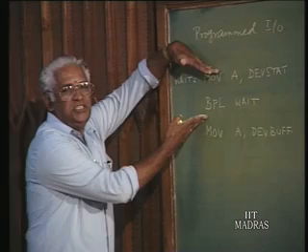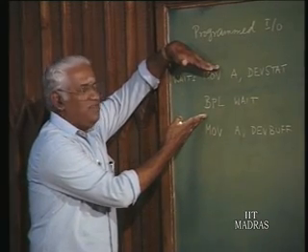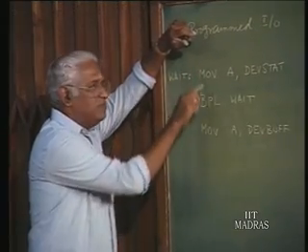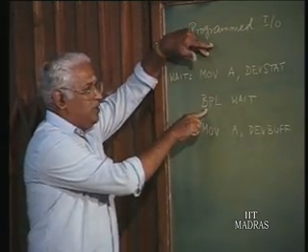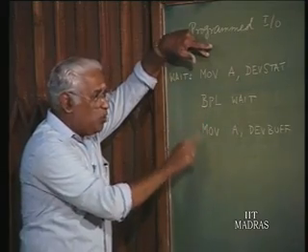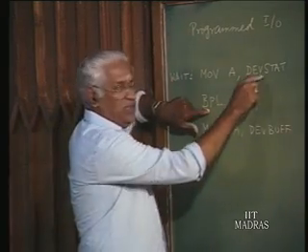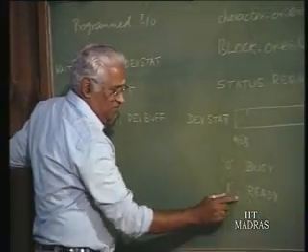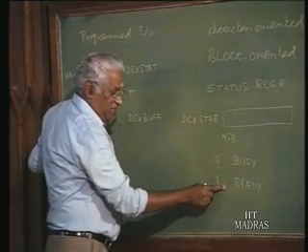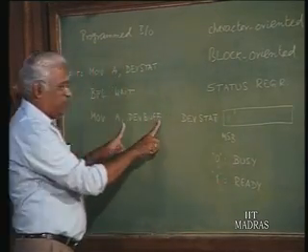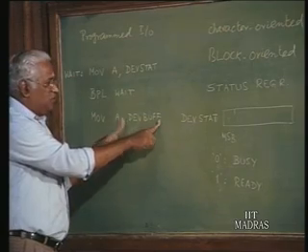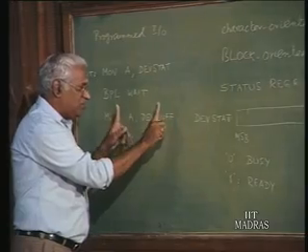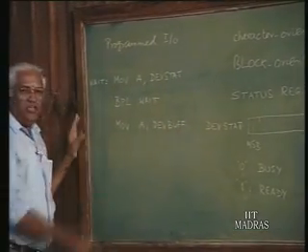So, these two are for checking the status and seeing whether the device is ready. If the device is not ready, as per this program it is just going to loop here, it will keep waiting. So, this instruction will be taken up only if the incoming word is negative, and that will be negative if the device is ready. The device indicates that it is ready when its buffer has the data. So, at this point when it comes, it means that the device data buffer is having the data which is input.